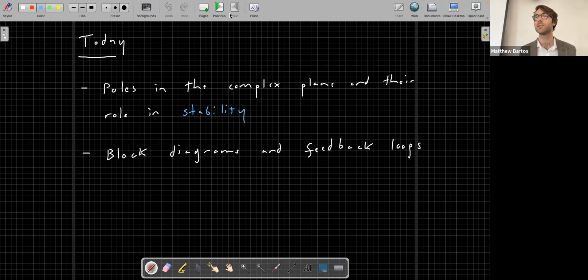Did you have a question, Jimmy? Sorry, so on the last slide, when you talked about conjugate pairs, I don't remember explicitly saying that the poles have conjugate pairs. Right. So when I say conjugate pair poles, it's if you have a set of poles that are complex, that are conjugates of each other. So those poles that are complex will always come in pairs. And it just comes from finding the root of a polynomial that is complex.